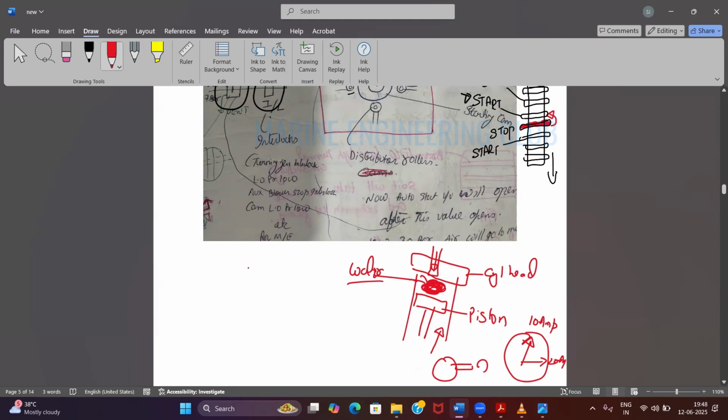You have to go and check then. Then you have to do the inspection part of your engine, right? So can we see all the units on the flywheel also, sir? Yeah, the flywheel also you can see where actually it is happening. Look at the pointer, correspondingly which unit it is, but it doesn't mean that only that unit will be the problem. It could be some other unit also. Pistons are not up for only one unit. Agreed?